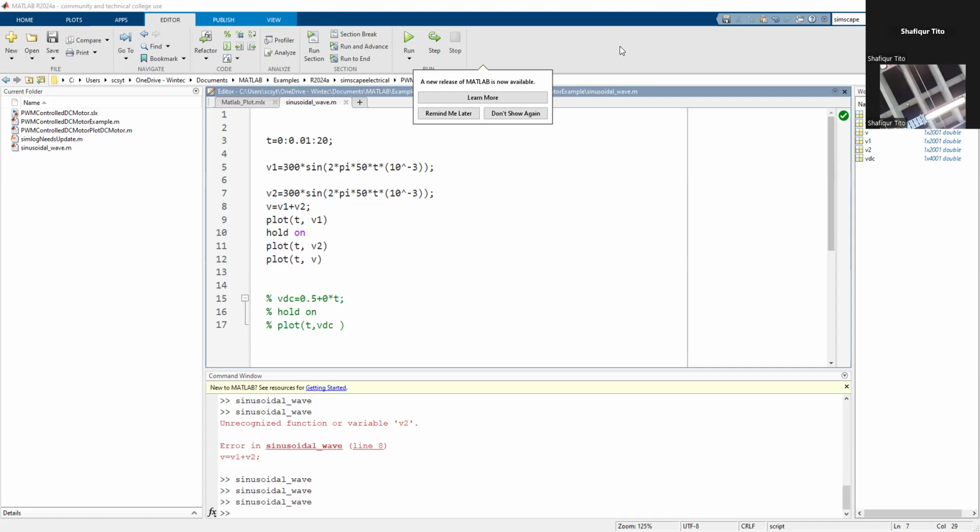But whenever it is AC, how many characteristics do we have for AC? Actually 3, but for the power system, the frequency is always the same. So 2 other properties: one is magnitude, another is the phase angle. If somebody asks you what the characteristics of a sinusoidal signal are, changing direction is the physical property, and for mathematical representation it needs 3 different characteristics.